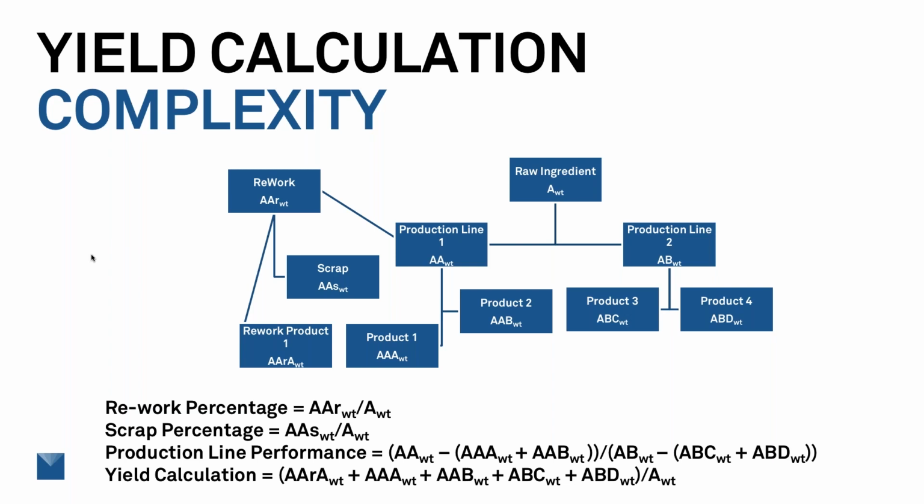And we need to know and track the amount of that rework product that gets sent out. In a lot of cases, the rework doesn't get run separately. It just gets put back into the production line. And so in order to be able to fully understand the system, the requirement is to lock in the identity of this material as it moves through the system so that we know where it's linked back to.